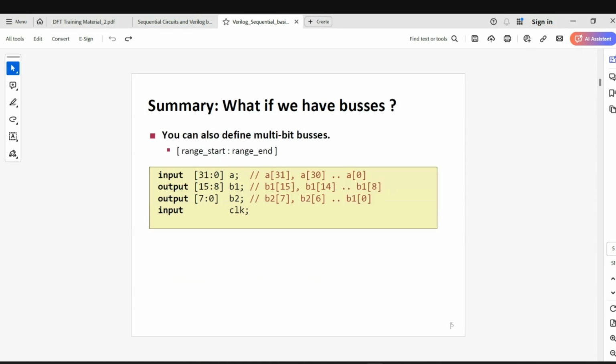Next thing. In the previous image that you have seen, we haven't defined any data bus, the bit length of the port. Here we are defining it. Input [31:0] a means that port a has a 32-bit length. So the data you can give using port a is up to 32 bits, like 101010, likewise up to 32-bit data as the input. That bus information you give in square brackets from the higher end range to the lower end. That is how you represent it here. Is this clear?